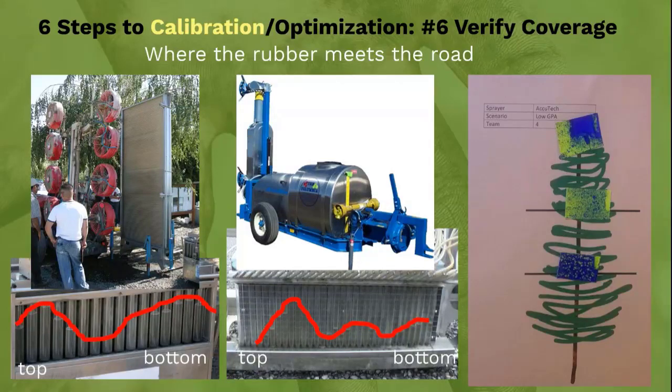So we thought we had these 2 great tower sprayers working really well and set for a fruiting wall, but we put them and tested them on the patternator, but it was obviously very wrong, because for a fruiting wall, you would want even coverage. What we see is this red line having a lot at the bottom and then curving down to not very much, and then a lot again for at least the multi-head fan sprayer, and then the one on the right, it curves up and down.